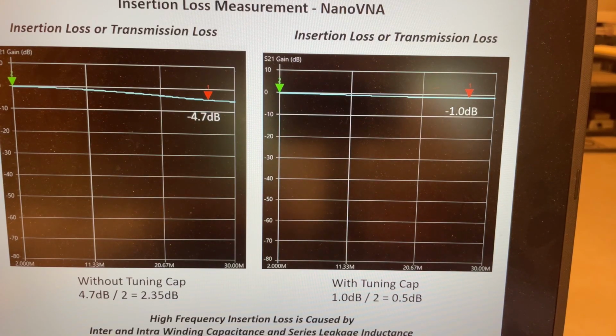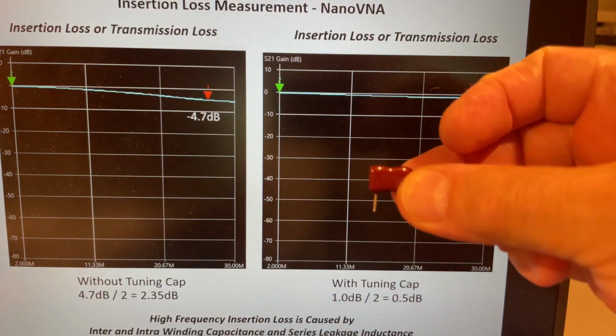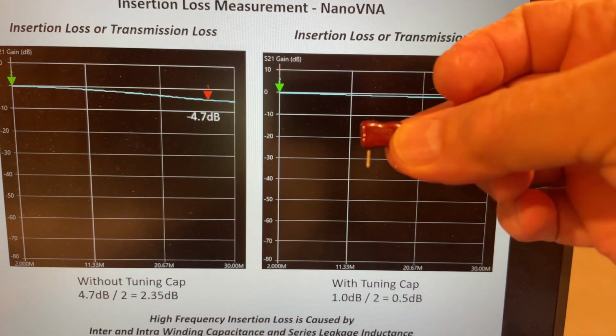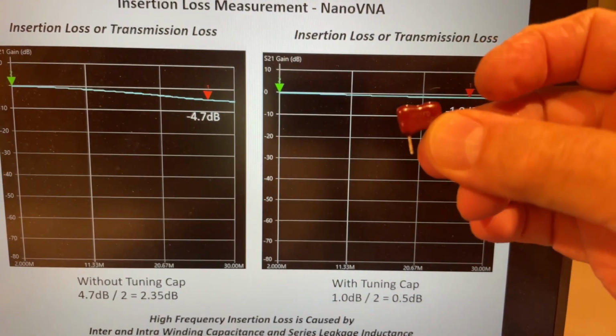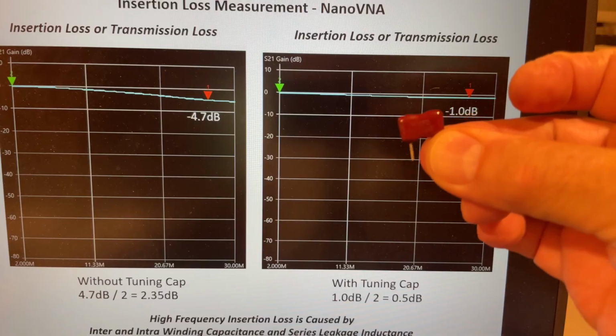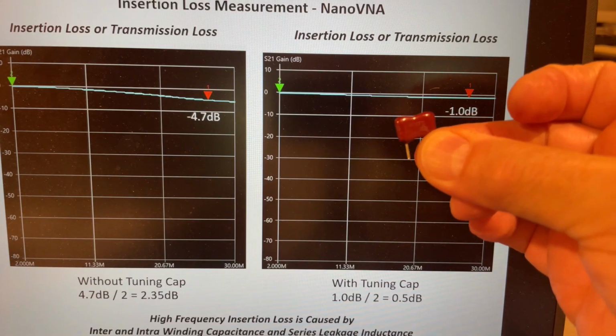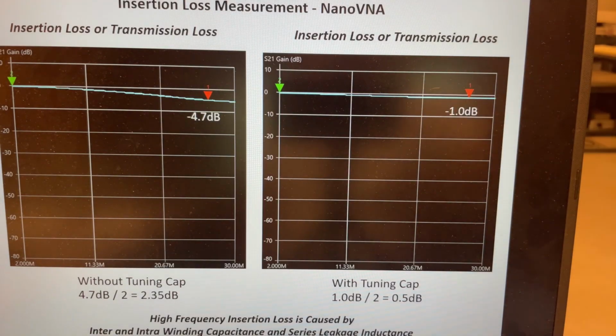I'm using a standard silver mica cap that you see there, and just had a number of values. Obviously, I tested this ahead of time so things would go right during the video. And it appears that 680 is the best optimal value.